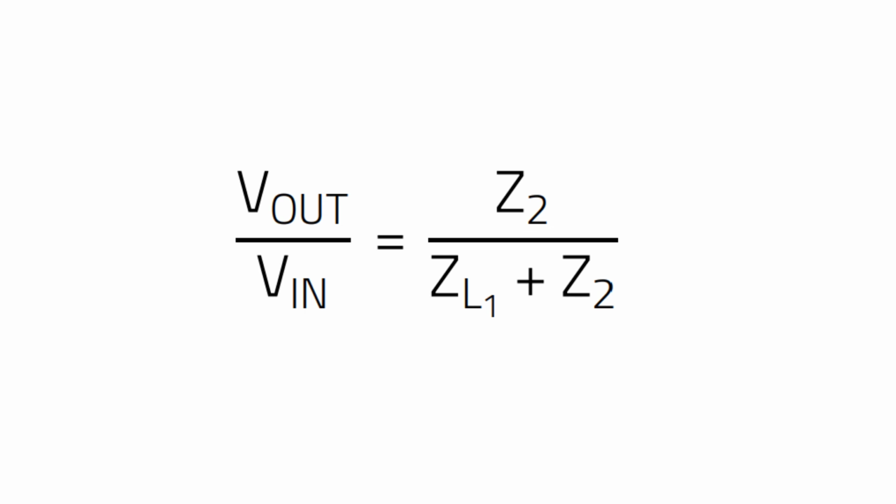So we know that our impedance is roughly 25 ohms, and therefore the capacitance needs to be around 250 picofarad. The operating voltage of the varistor must be greater than the maximum operating voltage of the system, which here is 5 volts. So considering a safety buffer of 15%, the maximum operating voltage of the varistor VDC is greater than 5.75 volts.